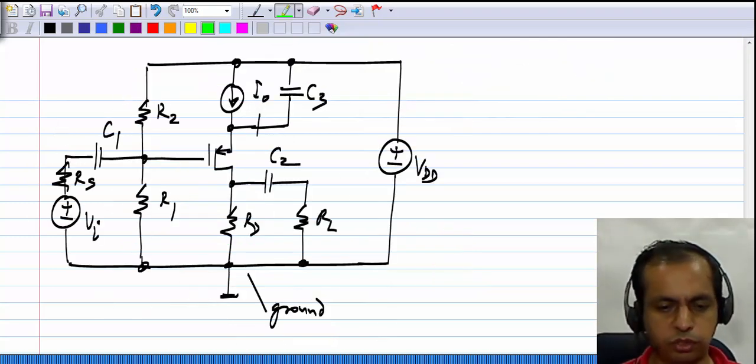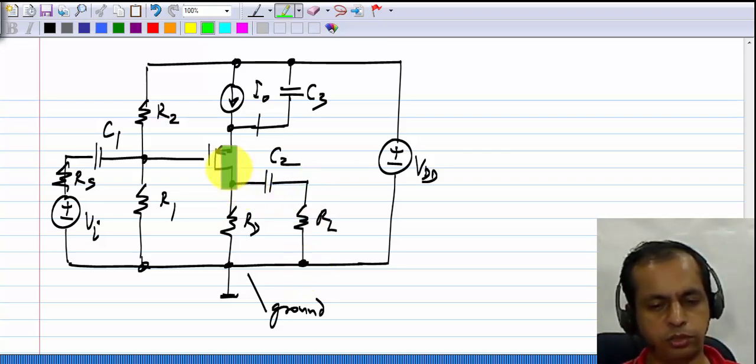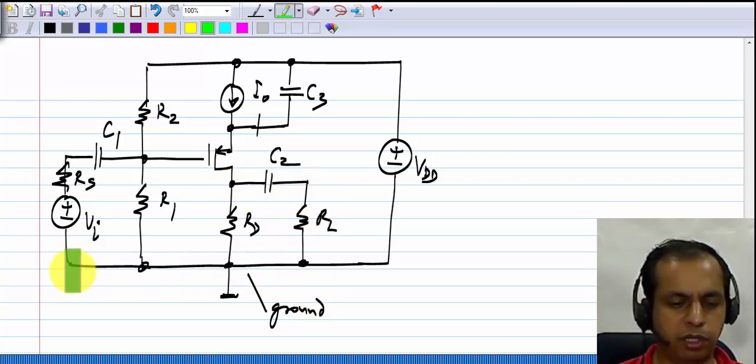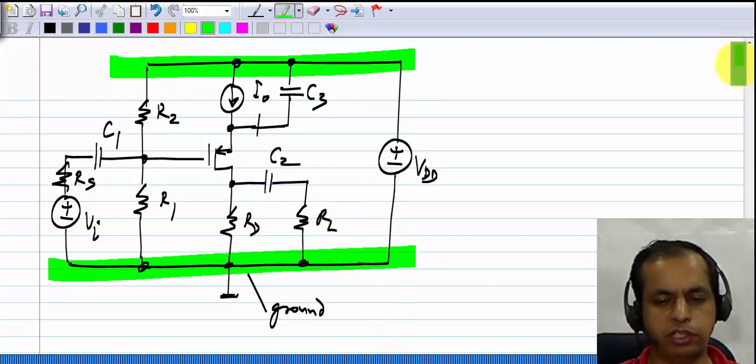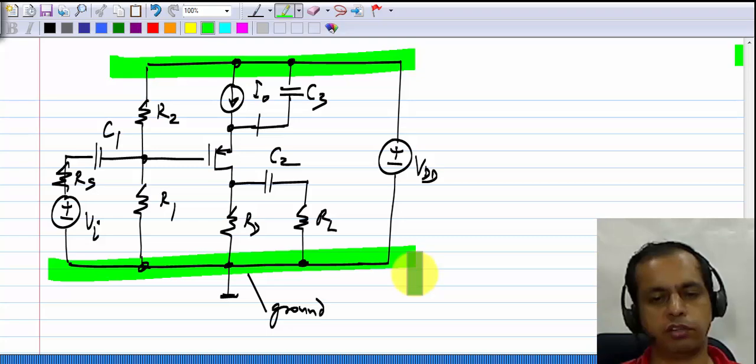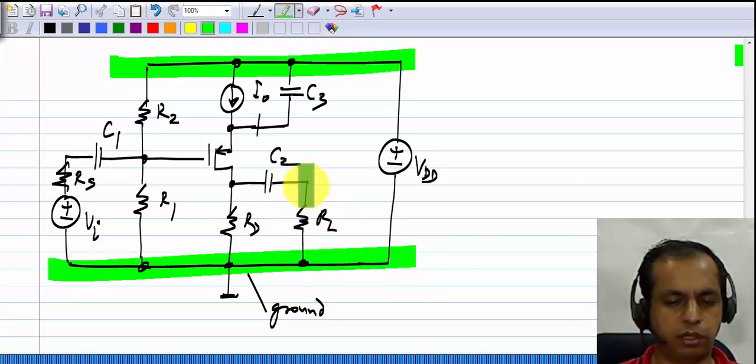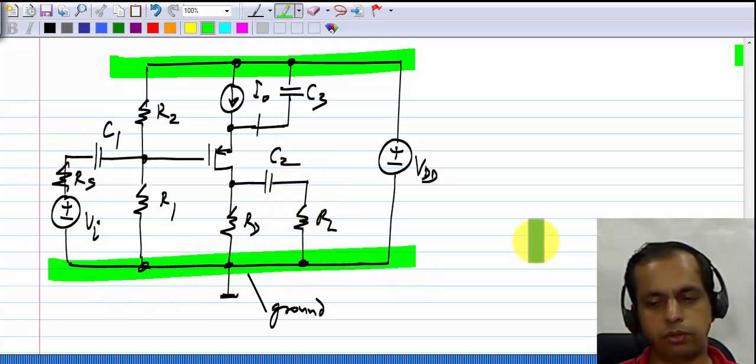But then when you change it to the common reference ground later, it is going towards the drain of the MOS transistor. But it makes absolutely no difference, because these two are at the same potential small signal wise. But because this is the common reference ground, it is common to return both the load and the source to this ground. Okay.